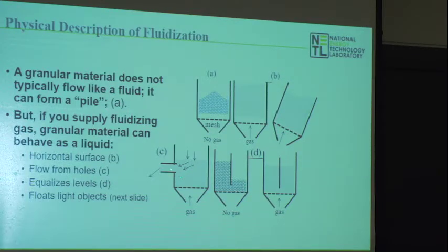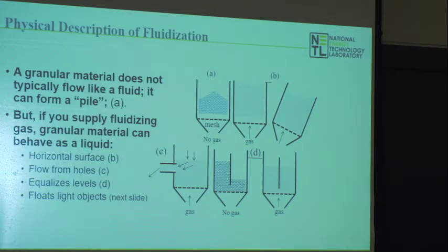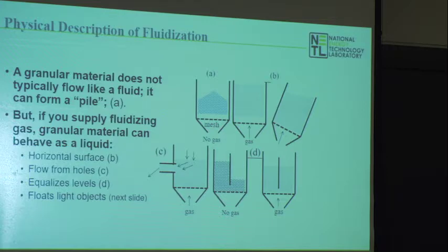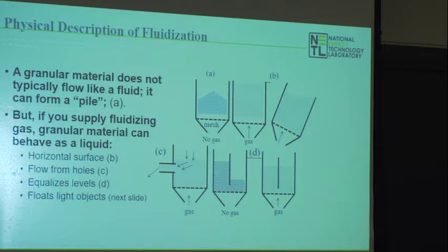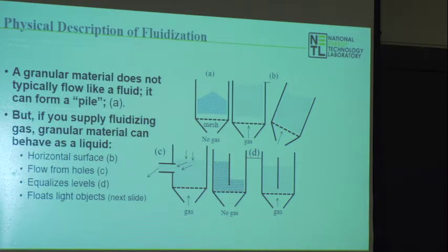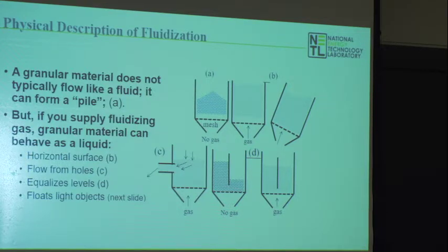It's even more interesting if you punch a hole in the side, the material will start flowing out of there like a fluid. Or if you put a weir in the middle of the device and you initially start with these two surfaces not being even, if you wait just a second after you fluidize it, they will come and equilibrate just like a liquid fluid. That's why this stuff's very easy to understand if you just go back to it's a fluid. It's not solids and gases. It's a fluid once you get it in a fluidized state.